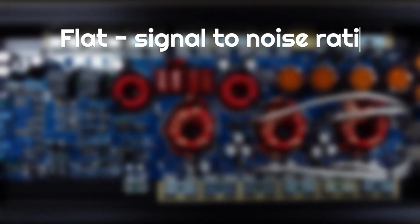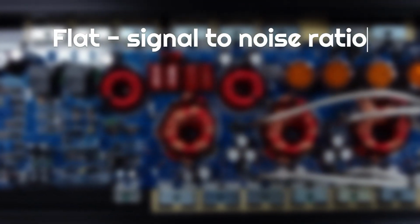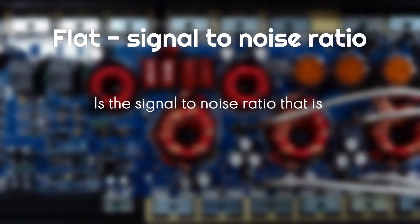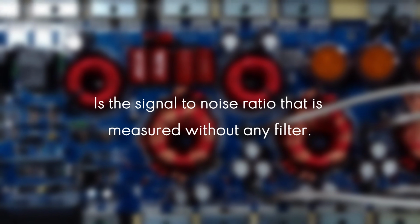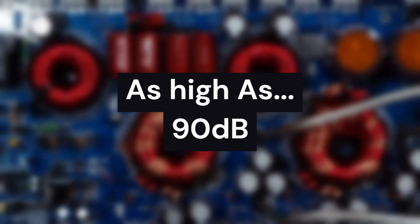Unweighted signal-to-noise ratio, also known as flat signal-to-noise ratio, is the signal-to-noise ratio that is measured without any filter. Weighted signal-to-noise ratio is more relevant and realistic than unweighted signal-to-noise ratio, and it should be as high as possible, preferably above 90 decibels.